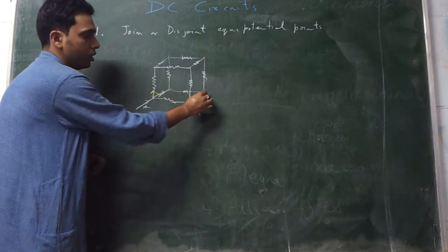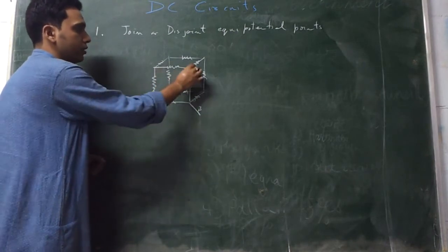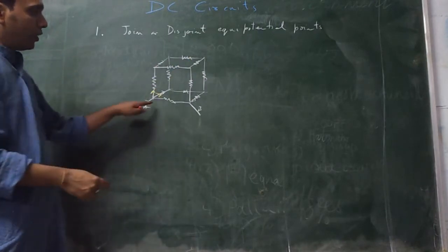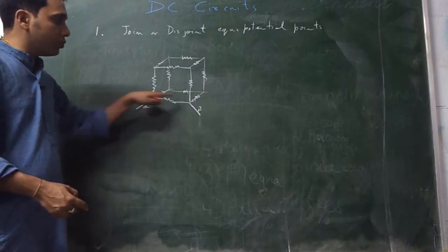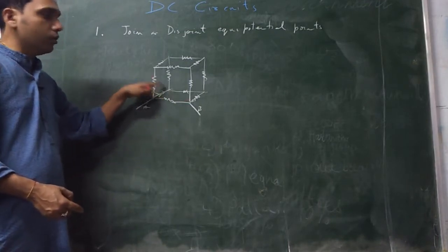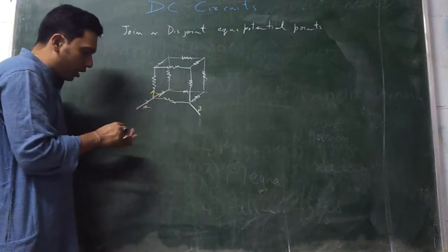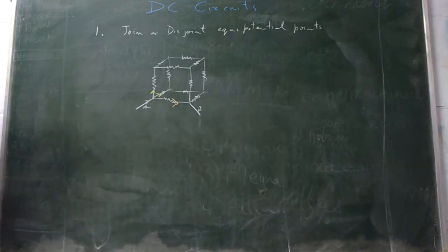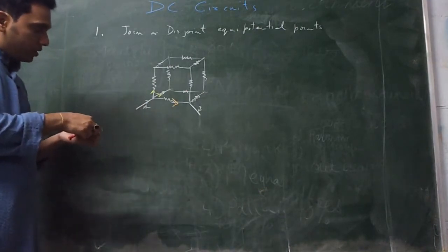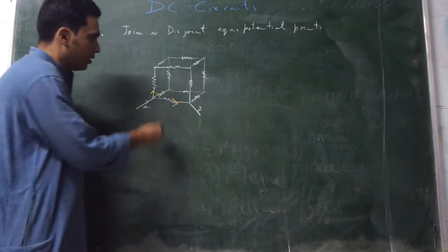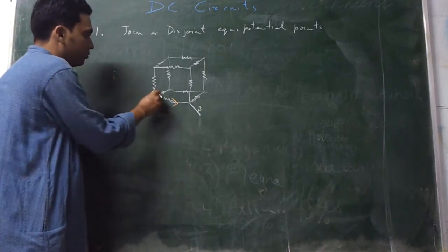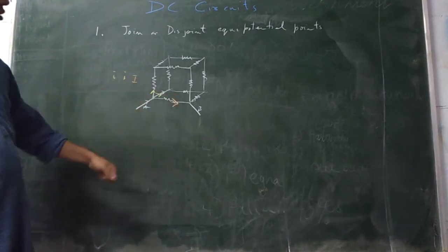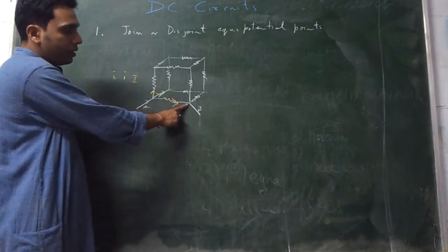Here same, it is going through a square path, part of a square. This also has a squarish path with the choices when it has. So this current is exactly equal to that current, which is not equal to this current because this path is not as this path looks like. So this path you can't just by seeing the circuit say that it's the same current. So the orange current is something else. Now by symmetry of the circuit we can say one more thing, that if yellow was I, then this is again I current and this one is say capital I. So two small i's plus one capital I is going. One capital I comes back to B.